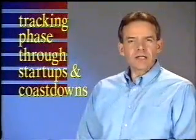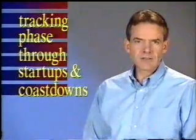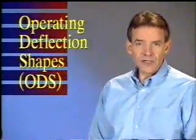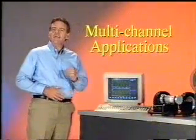Other single-channel techniques include tracking phase changes during coast downs or startups to determine the resonant frequencies of a machine, and a brief overview of using phase data for operating deflection shapes, or ODS. Multi-channel applications illustrate the techniques to calculate phase relationships from two simultaneous plots and display a phase spectrum. First, let's look at what phase really is and the ways it is measured.